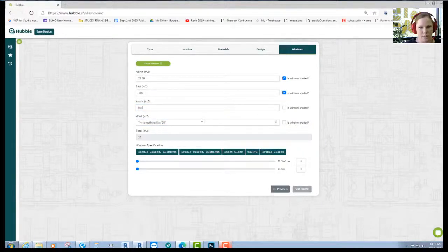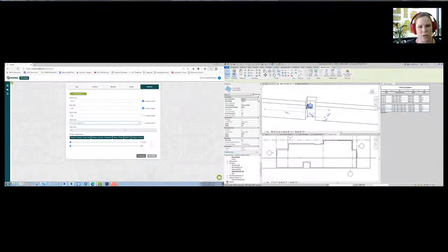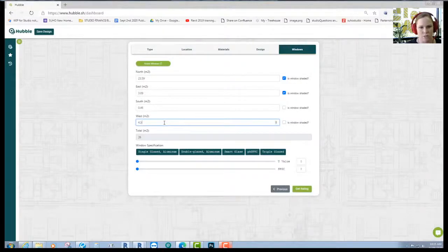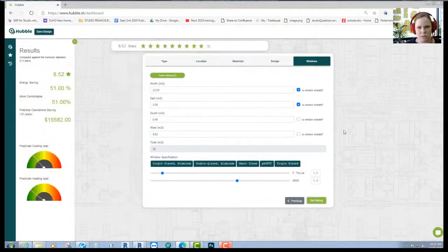West also. Now generally on most of the buildings that we'll do, you'll find that we are asking for shading on the north, east, west, although sometimes on buildings it's not required. It does give the occupants that level of adaptability to their comfort level, especially on west facing. Okay, in here I can actually put the actual U values now.